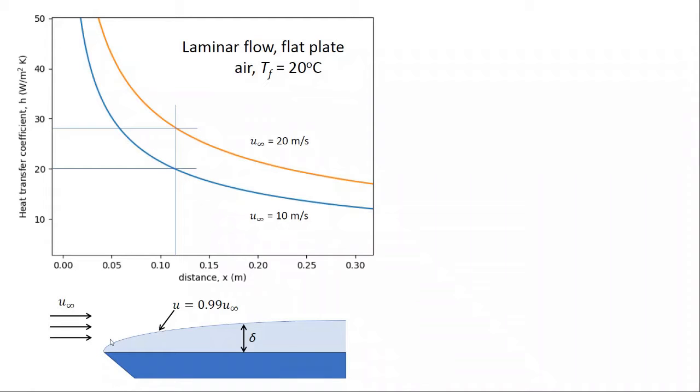Basically, at the leading edge, the surface is able to quickly remove lots of momentum from the flow. Back here, further away from the leading edge, the surface has to allow that momentum to diffuse through a much thicker boundary layer before it can remove it from the flow.